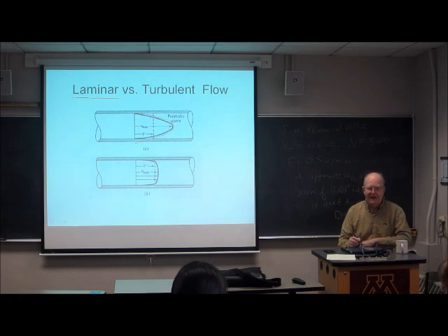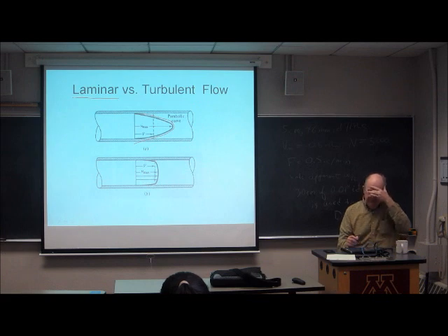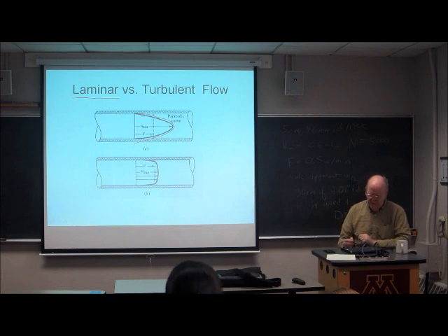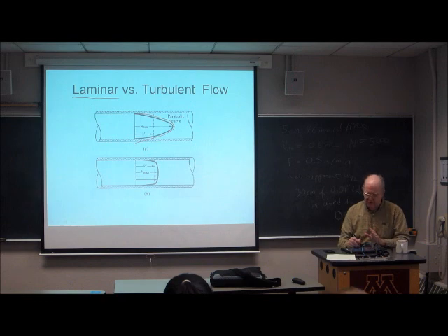It starts to flatten out. And you have to get to extremely high velocity conditions in order for it to flatten out even this much. But this has been drawn to represent pretty closely what goes on under turbulent flow. And that is the radial differences exist only right close to the wall, and in the middle of the tube it's essentially flat.